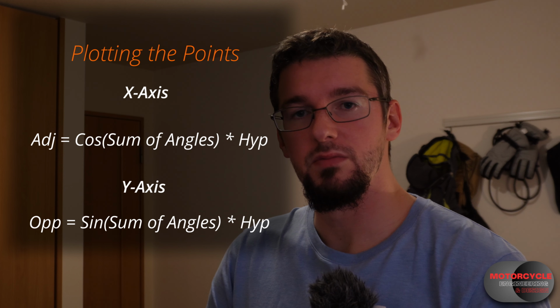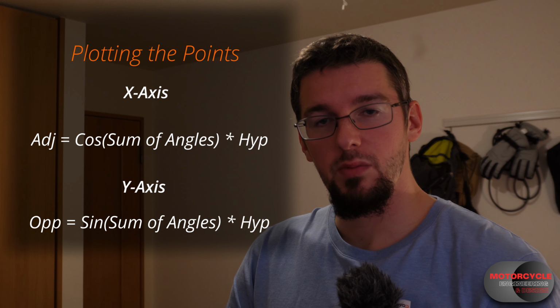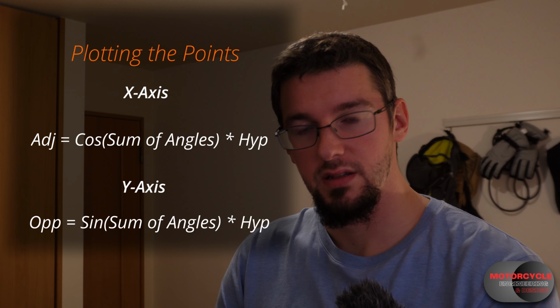Now that all the triangles are solved, we need to start plotting the points, and we do that using cos and sine from SOHCAHTOA. The important part here is to make sure that we sum up the angles correctly as we move from one point to the next.